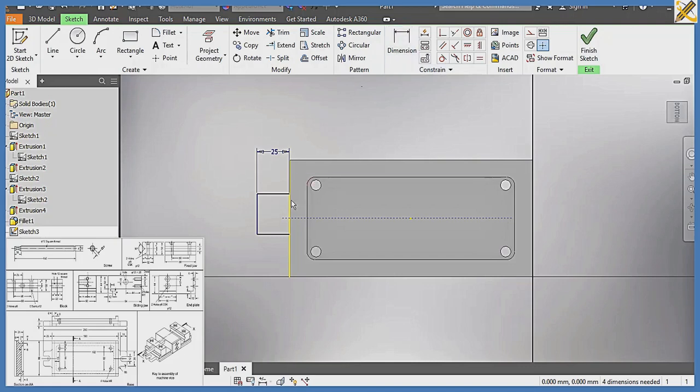And the span right here is 36. Enter. Okay, so I'm going to pick my symmetric constraint, this then this. So settled, escape. So what's the next thing I'm going to do right now? I'm going to pick this. So I'm having a radius 6, diameter 12. All right, so picking my circle, standing at that center right there, circle of diameter 12, enter.